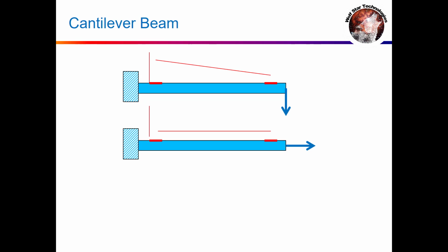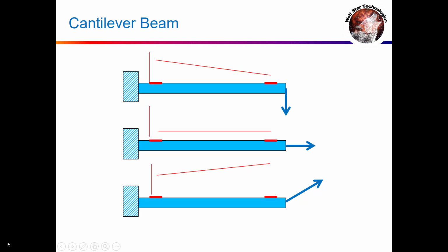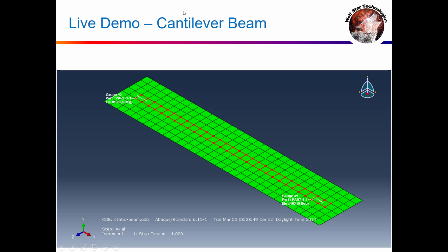And then if you look at a general loading case, your strain signal might look something like this, and then you can take that general loading case and break it into so much axial plus so much bending. And this is what TrueLoad does. So if you go into TrueLoad, TrueLoad will tell you to lay strain gauges at the right theoretical position. So let's go in and do that for real in TrueLoad.